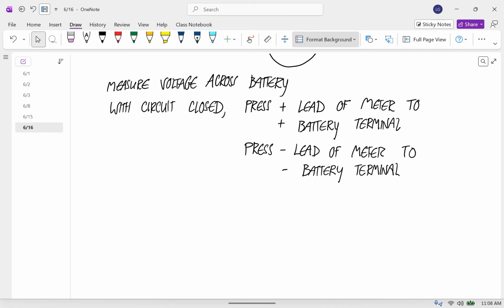Also, we have current coming out of the battery, and remember I was talking about the car battery thing yesterday, that what a big battery is really good at is producing a lot of current. It's not really having a higher voltage. So as you draw current out of a battery, that voltage will go down, and if we drew more current out of it, the voltage would go down more, and you would notice it on the meter. What did you guys get for a voltage? 9.15. Okay, so all different than 9, but all somewhere around 9.